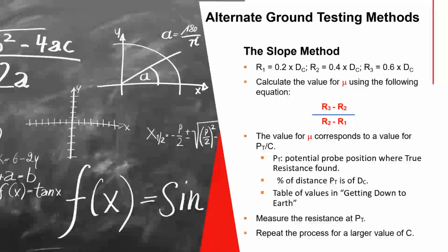And that can happen, especially with very large grids and with very bad grounding conditions where the electrical hemisphere of your grid is really large and your current probe's own test field is contained completely within that grid. And so you won't find a mu value on your tables. It tells you to start over again and try it again. So next.